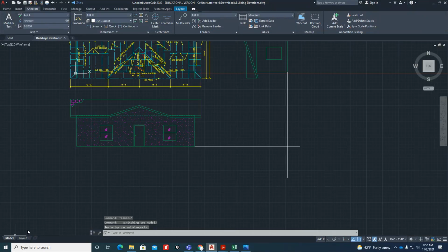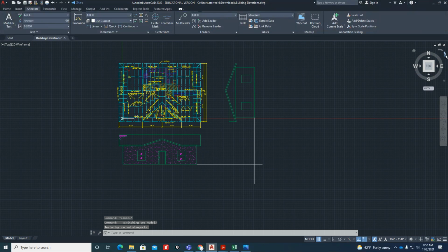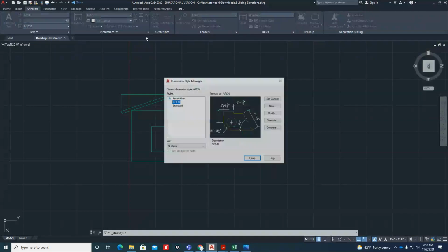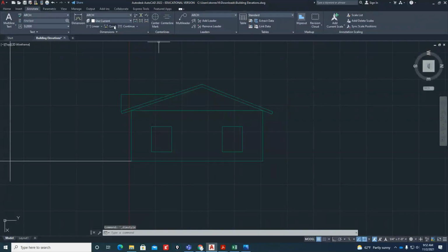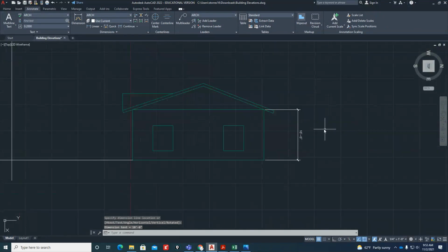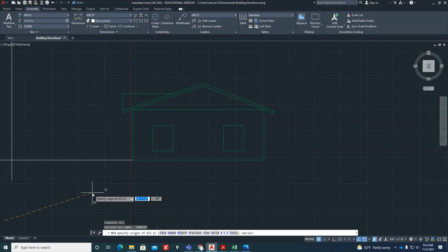The only other thing you're going to have to do is whenever you start labeling on this viewport right in here, whenever you put a dimension on this one, you might have to change your UCS, because when you go in here to annotate dimensions, for example, I'm going to try to show you that you do need to, in some cases, adjust your UCS, because sometimes these dimensions are going to come up backwards. Okay, so if you want it to be legible from the right side view, you'll have to use your UCS command and set a new UCS based on this view.